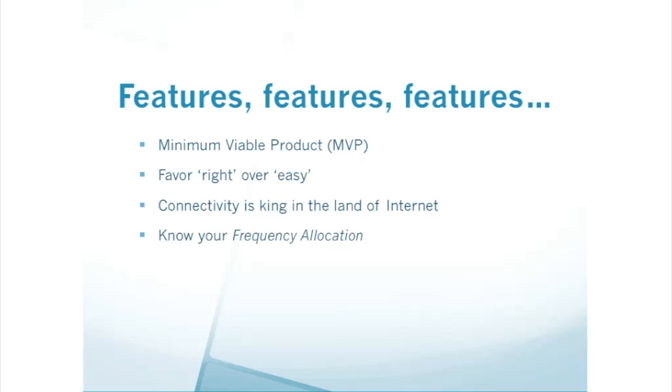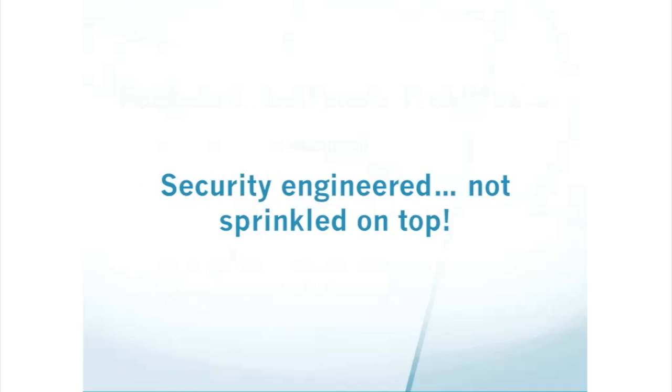With regard to frequency allocation, do think about those frequencies that are more available. And they might be sub-GHz frequencies, but because they are global, it means that you will have to produce less parts, and that those parts are going to be more interoperable with a larger consumer base. Definitely something to consider. And then also minifying your data. Big features are great, big protocols are great for when they're needed, but if they're not, then simplify. And then do give MQTT a look. It's a great option. So now on to our third section here about security.